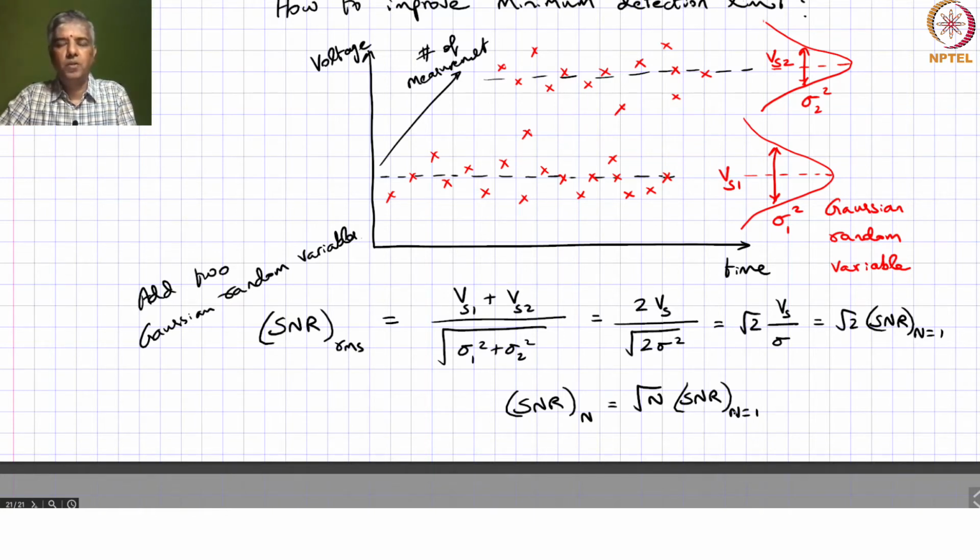To improve it, you send one pulse, you get a backscattered trace, you wait until you collect all the samples from the farthest end of your sensing fiber, and then you launch another pulse and get another backscatter trace.